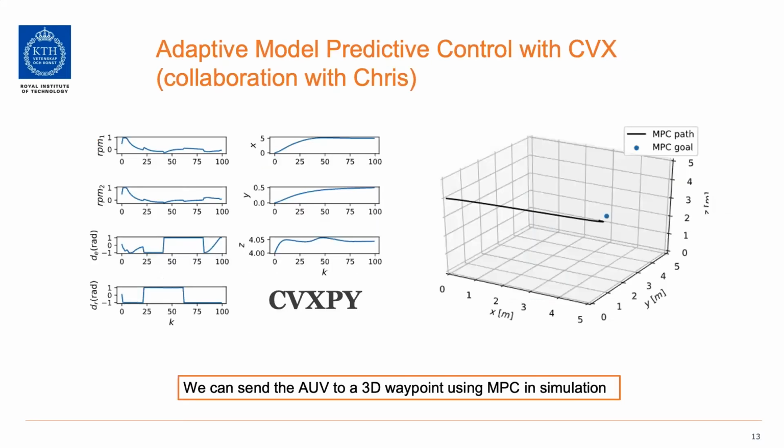So by doing this, you can see here that using that same model, I have simulated the model to go from 0, 0, 0 to a position, I think, 5, 0, and 5. And in order to do this, you first use the propellers to a certain extent, and then after that it stops, and it slows down because it already got a particular velocity, and then it uses its rudders in order to orient itself to reach that position. And what you notice here is these bang-bang features, which is quite common for optimal solutions in that sense.